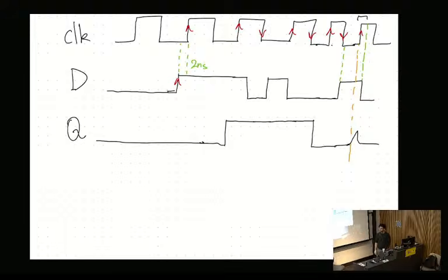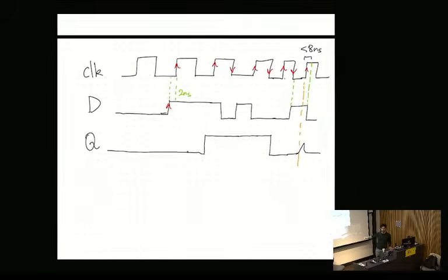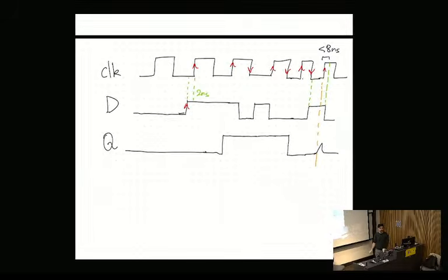And just for context, this timing notion is not specific to flip-flops and latches. The notion of setup and hold time is consistent with anything which has timing diagrams. Often you have to set it up, and then it has to be held at some point before it's then processed to the output. And everything has delays. Okay. Were there any questions on this?